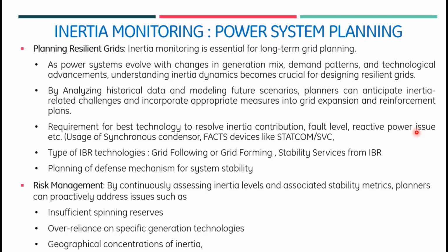They will also see what kind of technology is required to resolve the inertia contribution, the problem of fault level, the problem of reactive power, etc. In the form of devices like where to put a synchronous condenser, where to put FACTS devices like STATCOM and SVC. And then we have what kind of IBR technology you are going to use.